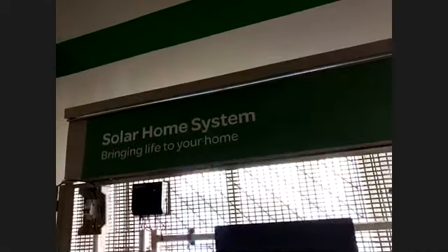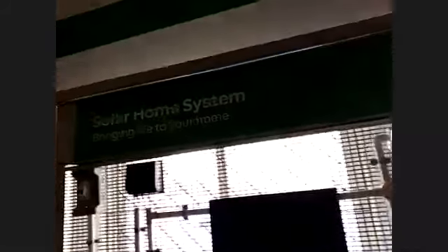In the first step, you have already calculated the total energy consumed by the system, that is 200 watt hour, and you must take the autonomy factor and good sunshine hours. According to your area, you must choose the good sunshine hours. For this station, I am using 4 hours of good sunshine. And regarding the efficiency of the charge controller, let's take it as 95%. This PWM charge controller has an efficiency of 95%.